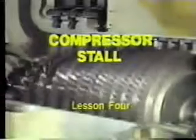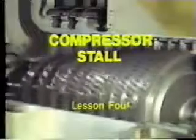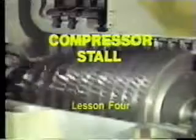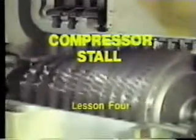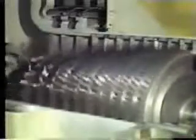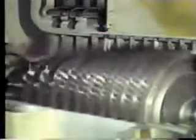This is Lesson 4, Compressor Stall. Before moving on to other engine sections, the compressor operation must be explained further. In the previous lesson, you learned how the compressor functioned at normal operating speeds. At lower speeds, however, the process of compression is not nearly so perfect. If not carefully controlled, it can result in failure of the compressor to pressurize air. This condition is called stall. This lesson will investigate the causes of stall and how it is prevented.